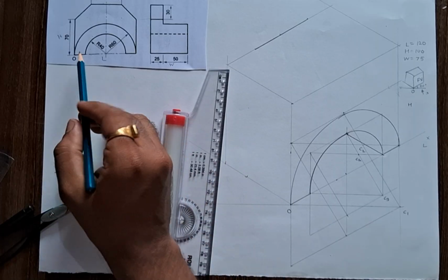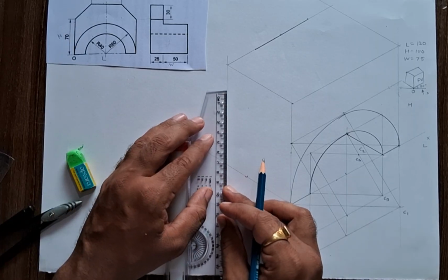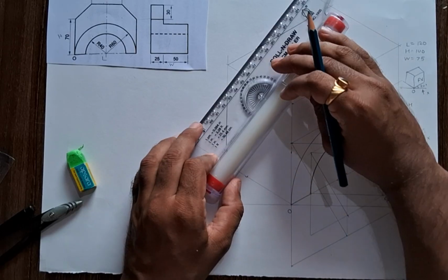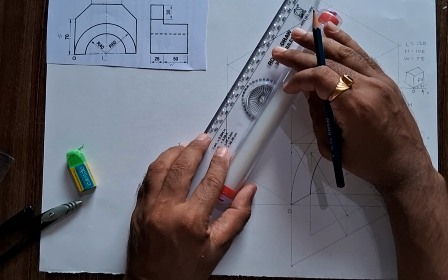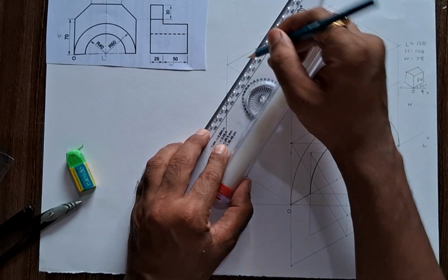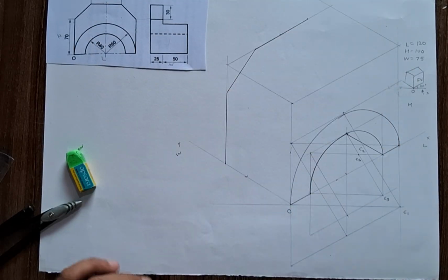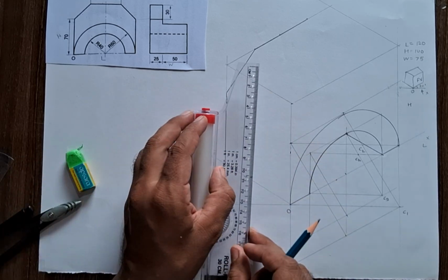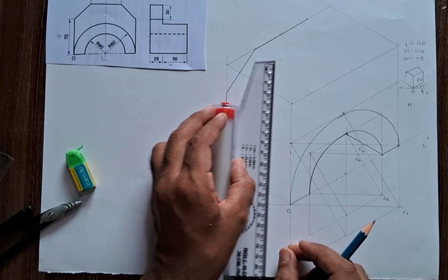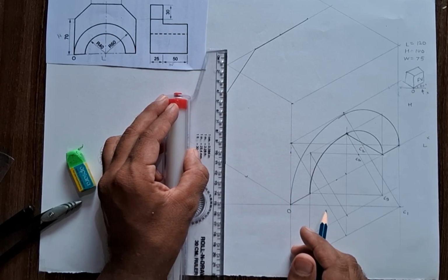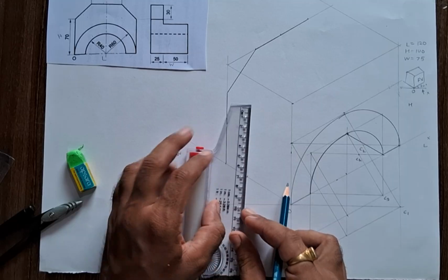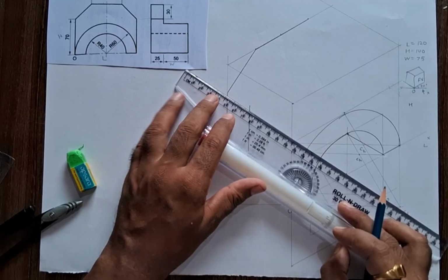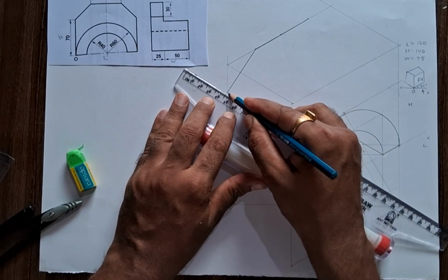Now this height, the vertical edge height is 70 mm. So from the back side we can mark a 70 mm straight line. So this edge, this slant surface we can see here, this is a slant surface. This slant line is a non-isometric line. Now the same vertical line we get at a 25 mm distance from the back side. Height is 70 mm. Height is 75 mm. This edge we can see.